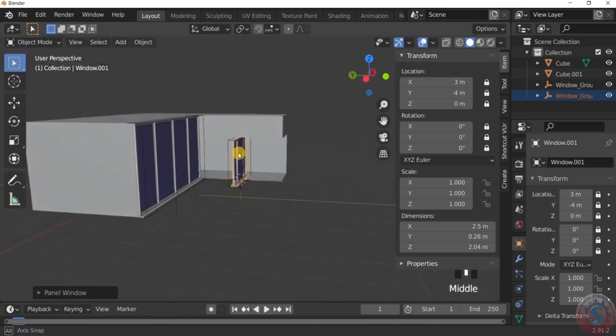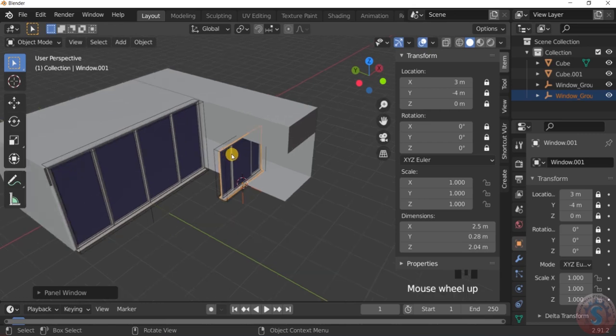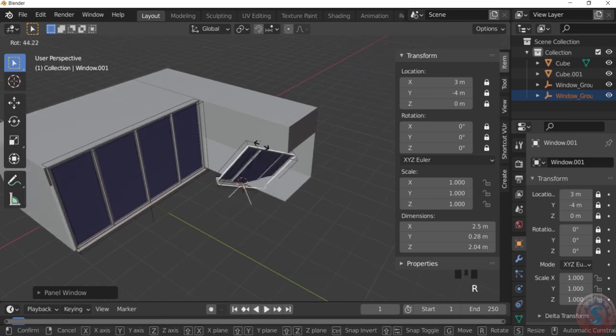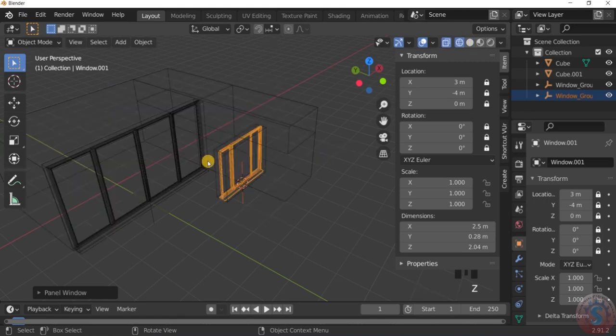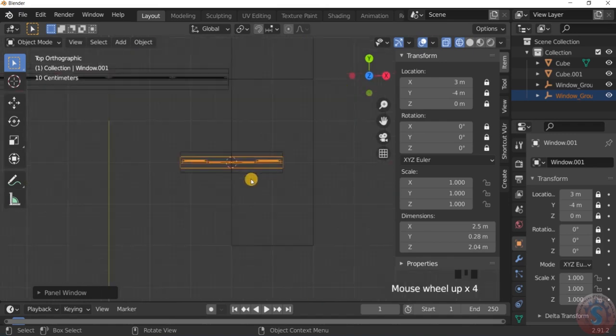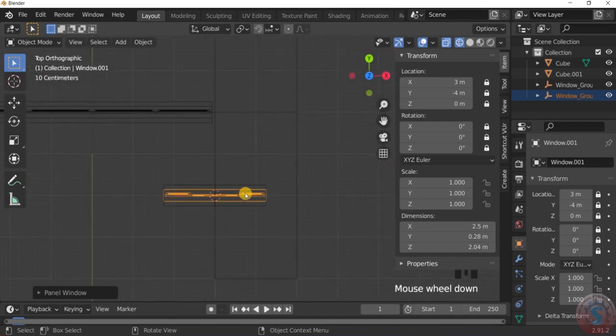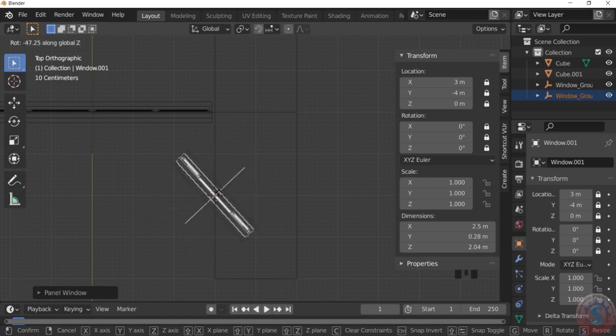on the position. Then I want to rotate this by clicking the R key, but it does not rotate like this, as you can observe. First go to Z on the wireframe mode and give the axis, and after selecting this, click R, and after clicking Z, the rotation is possible.